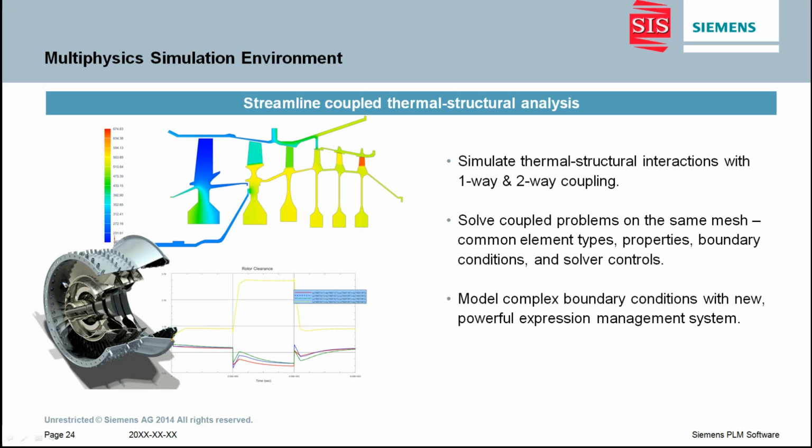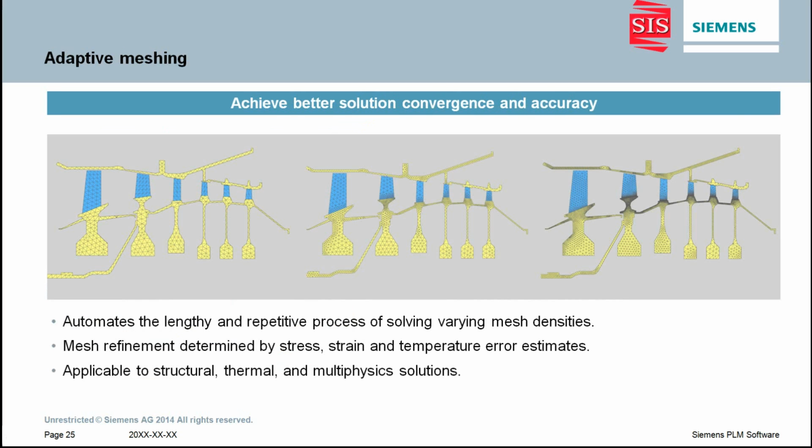This initial release of the multiphysics environment provides the ability to solve thermomechanical problems in loosely or tightly coupled modes. Coupled thermostructural analysis leverages the new NX Nastran SOL 401 multi-step nonlinear solver and a thermal solution from the NX thermal solver. Using NX 10, you can now more easily tackle complex simulations such as blade clearance analysis within aircraft engine systems or structural analysis of automatic powertrain components within high temperature environments. Other applications for electronic components and metalworking processes are well suited for the multiphysics environment as well.